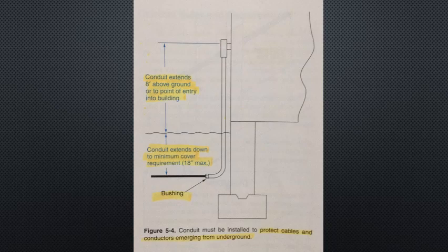Mechanical and electrical continuity is required. Metal conduit, cable sheaths, cable armor, and non-metallic raceway must be continuous between boxes, enclosures, fittings, and cabinets. All connections between the components must be secure prior to pulling conductors. The equipment grounding conductor should be independent of the device connection, so if the device is removed, continuity is not interrupted.